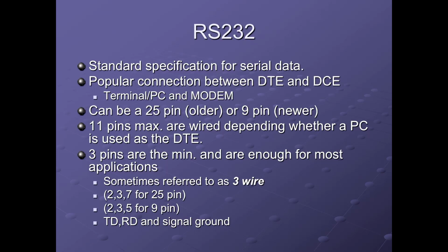I often tell my students, if you were to go out in the field after getting a job and having to work with an RS-232 device, if you found it to be 25-pin, it probably means that equipment is from way back in the 70s or 80s, and it's time to talk to your supervisor about upgrading your equipment or getting a new piece of equipment. It's a real telltale sign of its age.